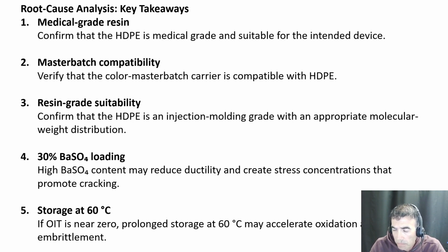I mean, there is always oxidation when parts are exposed to oxygen. Based off the Arrhenius equation, the reaction rate is just smaller compared to when you are melting the polymers. But the oxidation is there. It's just that the antioxidant and thermal stabilizer that you have is protecting the resin. If those thermal stabilizers and antioxidants are already consumed and are not there, the material is prone to oxidation. And even at 60 degrees C, if you increase the time, this could impact the backbones of the polymers, and it could impact the mechanical properties of the material.